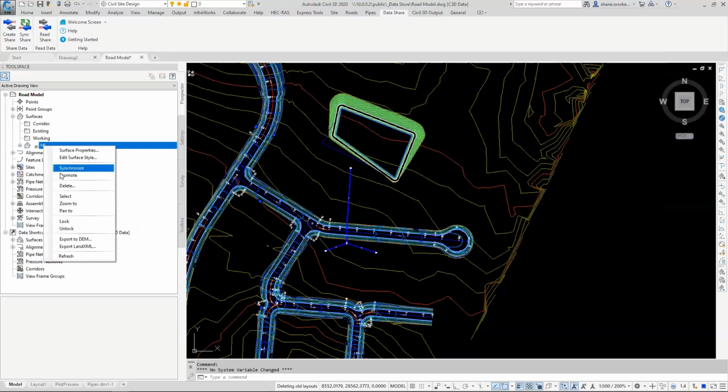Yes. We'd have to break it to show you the connection, but yeah, it gives you a little warning symbol on the item in the prospector, and you can choose to repair, and then if you don't get it right, it'll ask you to locate the original source drawing. So you go and find that drawing again, click on it, and then it would repair it for you in the background. I guess if there's any other questions, we can start destroying our world by doing exactly that, Todd.